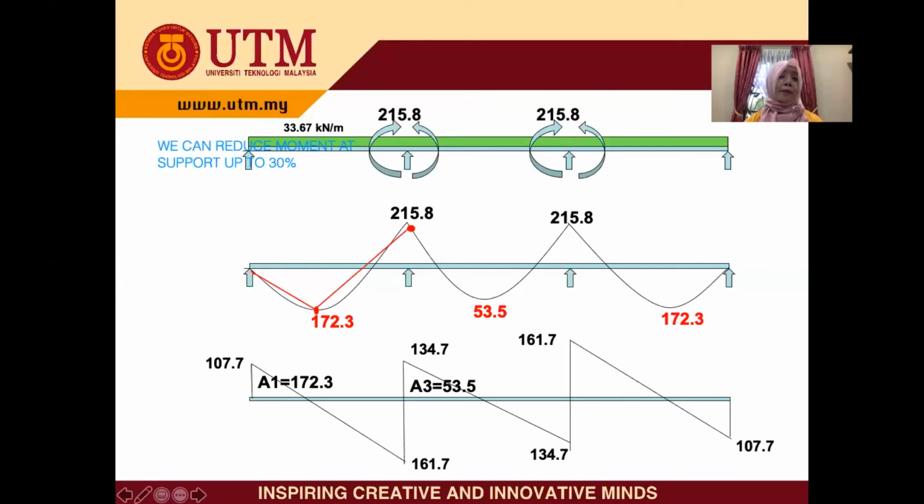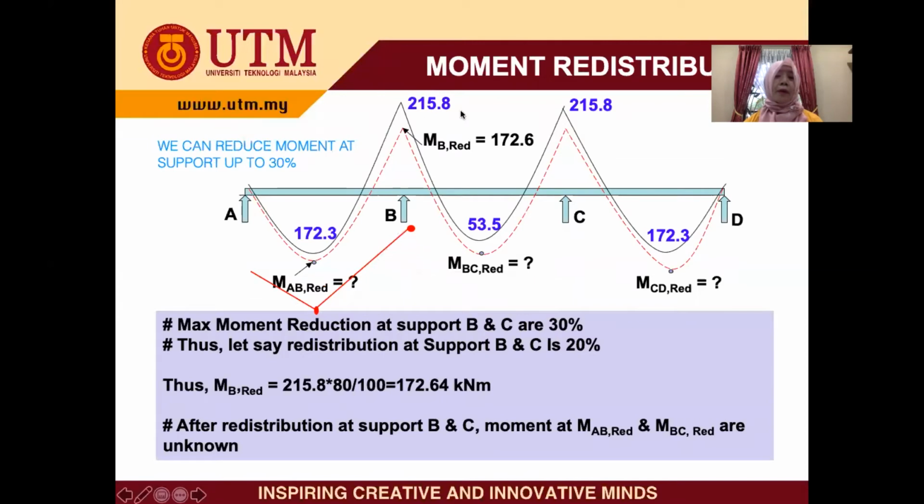Therefore, for design, we are allowed to modify the moment at the support, so that during ultimate limit state, hinge will form at both sides.